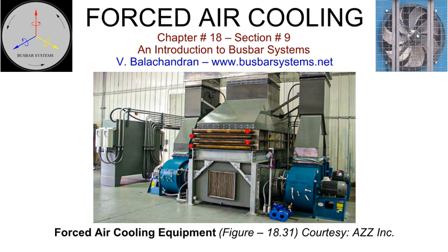The blower is designed for the delivery of a specified minimum discharge. The cooling of the conductor and enclosure is affected primarily by convection along the entire route length of the connection. Depending upon the airflow, the equipment can be classified under an open loop or a closed loop system. In the open loop system of forced cooling, the outlet cooling air from the isolated phase bus is discharged into the atmosphere. Consequently, clean inlet air to the cooling system has to be extracted from the atmosphere at a temperature not exceeding the specified air inlet temperature.